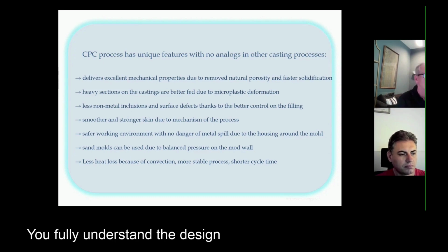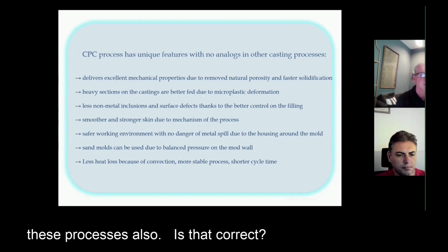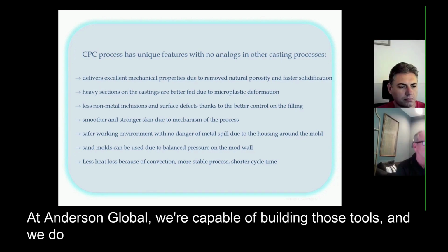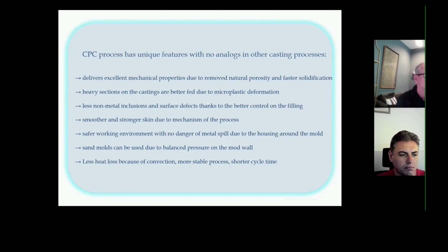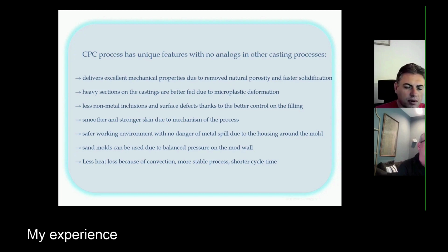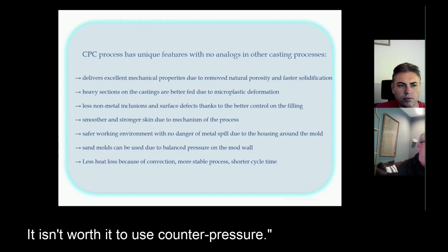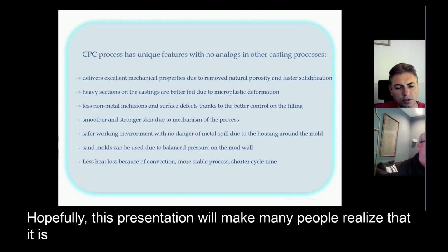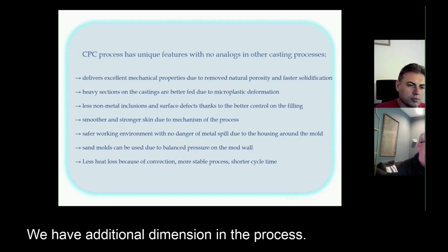You fully understand the design requirements of the tooling associated with these processes also. Is that correct? Yes, exactly. Anderson Global, we're capable of building those tools, and we do today build counter pressure tools. In my experience in the foundries, I often see people that neglect the difference between low pressure and counter pressure, and they say it is the same, it doesn't work to use counter pressure. Hopefully this presentation will make many people think that it is not the same, because it is really not the same. We have an additional dimension in the process.